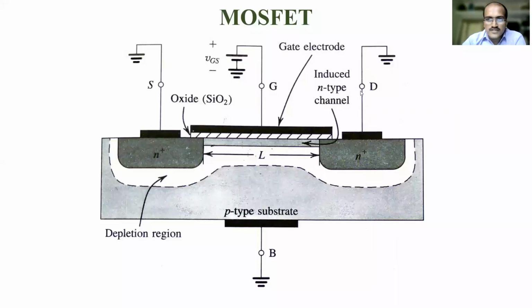Okay, so yesterday we have seen the device structure and the first step. If no gate voltage is applied, it could not form a channel here. It will provide a strong resistance so that there is no chance for current to flow from this region to this. So the very first step in MOSFET operation is you have to apply the gate voltage.